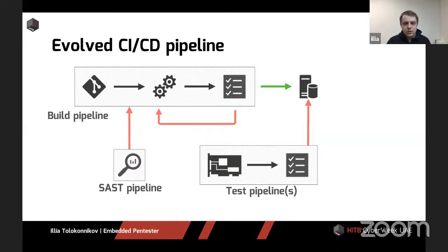And that allows you to develop at different paces. So you do not block, for example, the built-in pipeline with your week-long tests. And you can multiply the number of pipelines you run over that firmware simply by passing a pytest -m, which is short for mark, selecting that this pipeline should run tests for Wi-Fi, this pipeline should run tests for OTA, and this one should run tests for security.